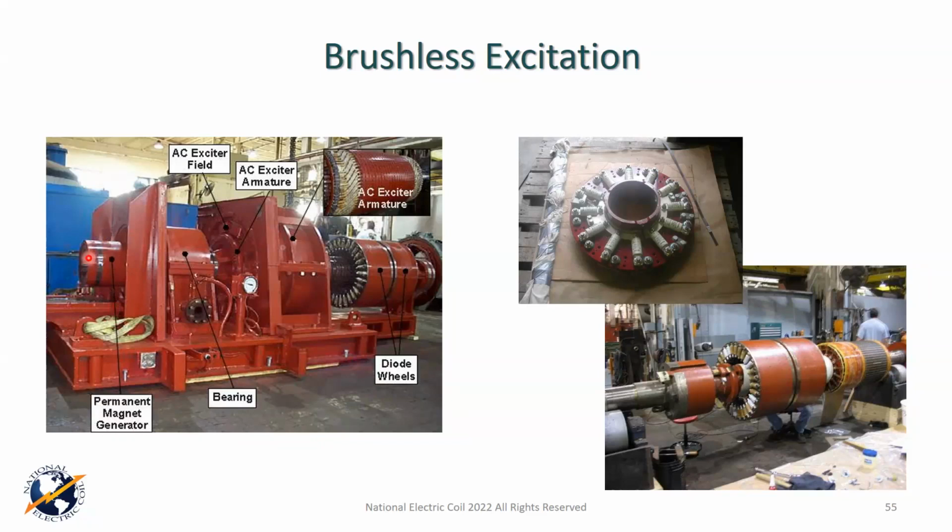So the permanent magnet generator that you see has a little armature, and it has these permanent magnets. That's the energy that starts everything off. It goes down through the armature, comes through the bearing, and then you've got that DC energy that's put into the field pole and then into the armature.